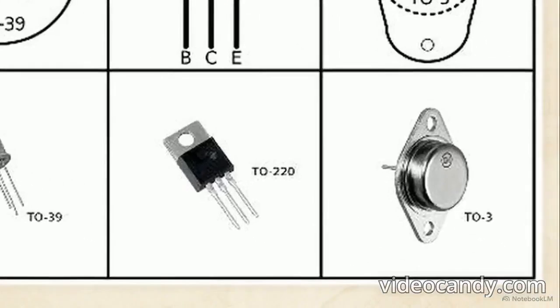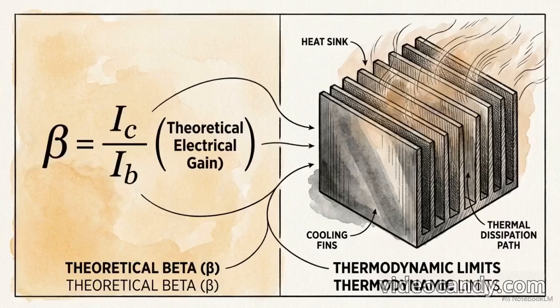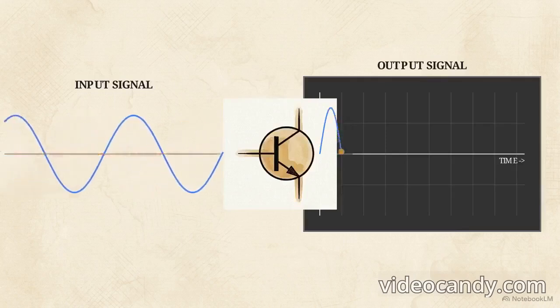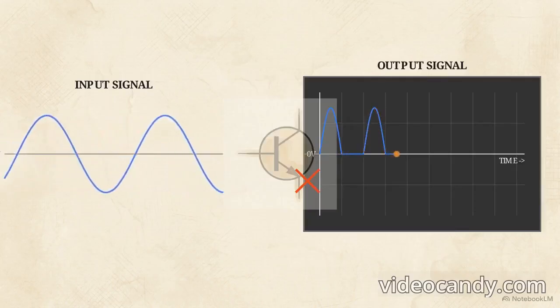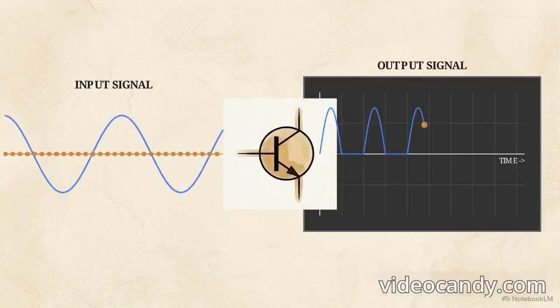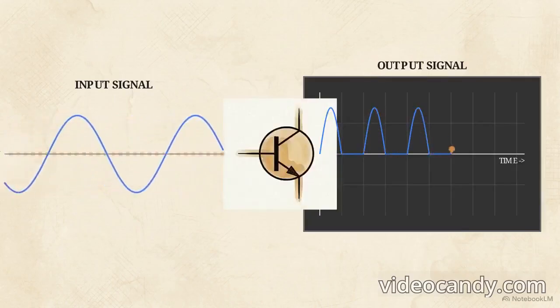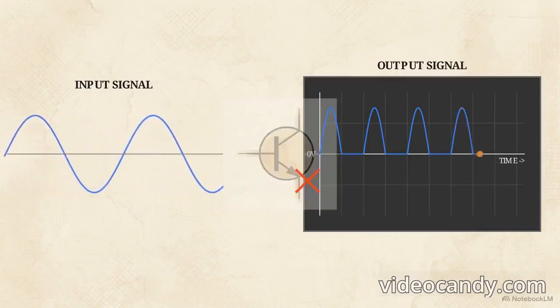Allowable power dissipation is tied to the package's physical footprint. A tiny plastic TO92 is limited to small signal amplification. To drive power and reject heat, engineers switch to a large metal TO3 package, using the casing as a heatsink to dissipate thermal energy. Every electronic design is a compromise between the mathematical requirement for gain and the thermodynamic limits